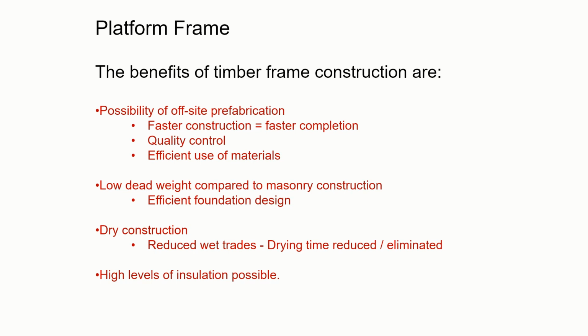For instance, you can't use mortar, or you shouldn't set mortar where there's a risk of it freezing, whereas a joiner can work in all weather. You can work in the snow and still the nail gun will fire and you can erect the frame. It's also possible to get high levels of insulation within a timber frame, and the diagrams to follow will show how that's done. But it's easier to get insulation without having to get a very thick wall by using a timber frame.